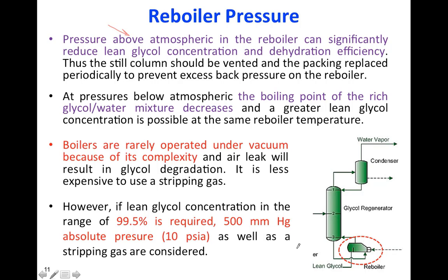This makes sense, because if I increase the pressure in the reboiler, I will make the escaping of water more difficult. If I increase the pressure here, the water prefers to stay in the liquid phase rather than come to the gas phase, because the pressure is high.